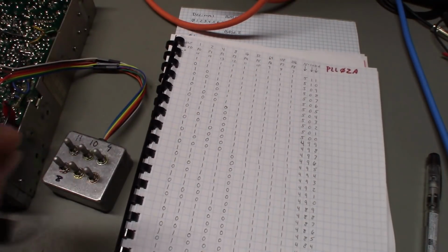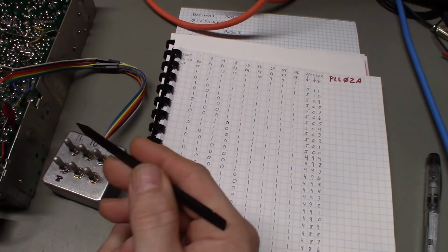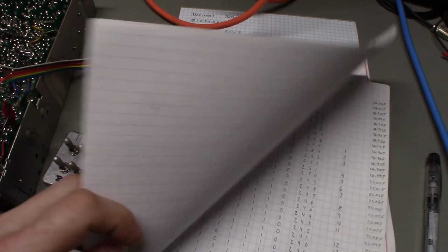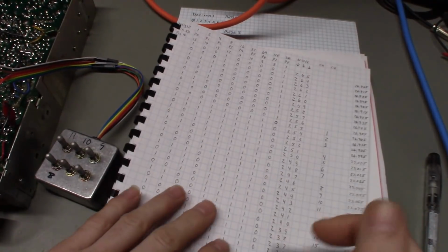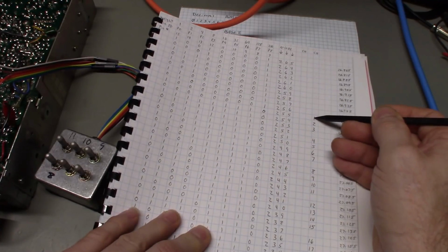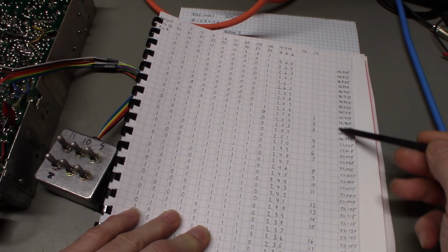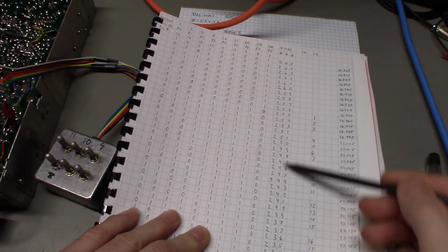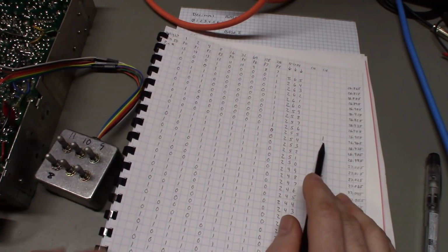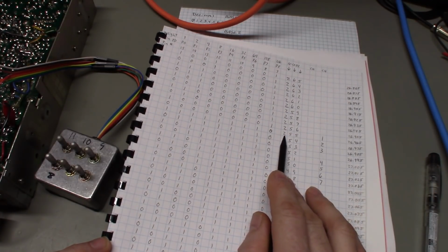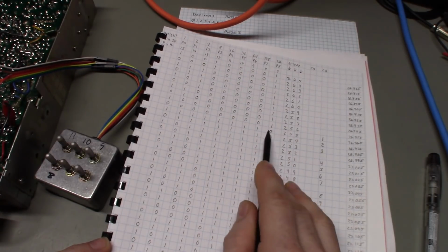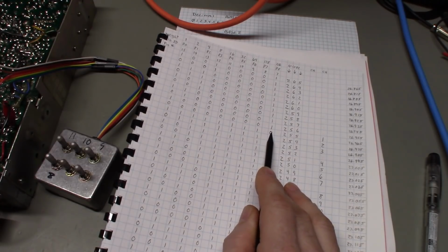There's a few other things I need to explain. This is an oddball PLL. One thing you're going to notice is, once I get back here, actually, this is the right one. I had the channel numbers written down here, and you can see I've got the frequencies written down over here. Here's our decimal numbers, or encode, and then here's our binary. You can see for channel 1, that is a decimal 255. And then this is the binary code for that. All ones except for a 0, the most significant digit.